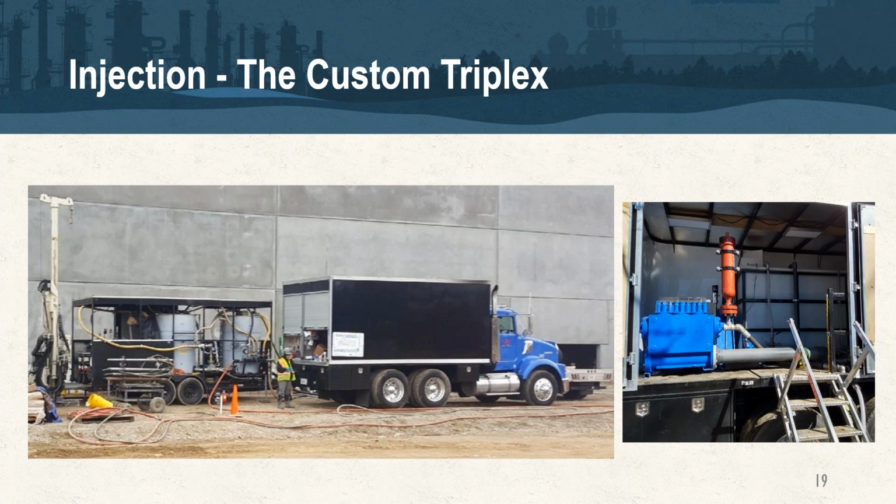So here's a look at the triplex pump. This is our custom truck, custom pump setup. On the right, that blue pump is our triplex pump. That's attached to our Kenworth T800 truck. And as you can see in the picture on the left, we've got a batching trailer as well. In this picture, we're actually using it for an overburden injection that was on larger 10-foot centers. We needed greater distribution because of depth, so we took the bedrock truck out there for this. So it can be used in that application as well, which is why I included this slide.